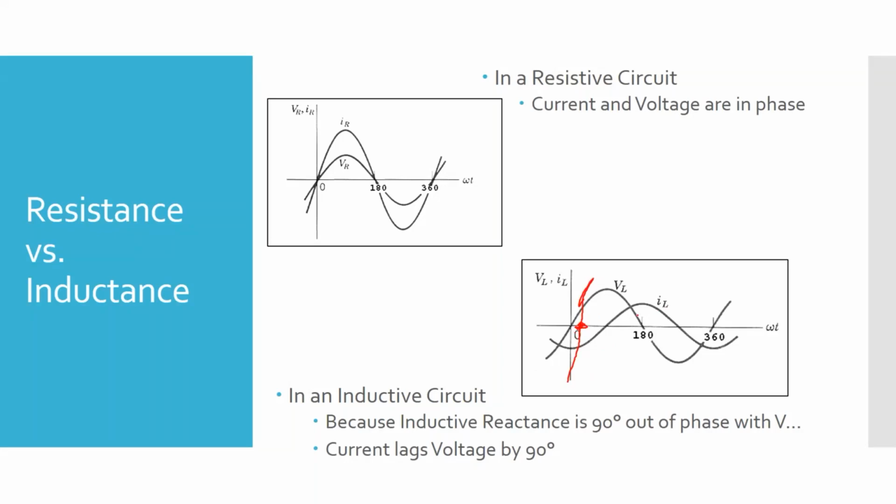And then you'll get the same thing over here, to the right, where in this case the voltage is negative, the induced current is positive, and so they're going to cancel each other out. That's why it acts like a resistance, because it's going to reduce the voltage going through that coil. So that gives you your inductive reactance.